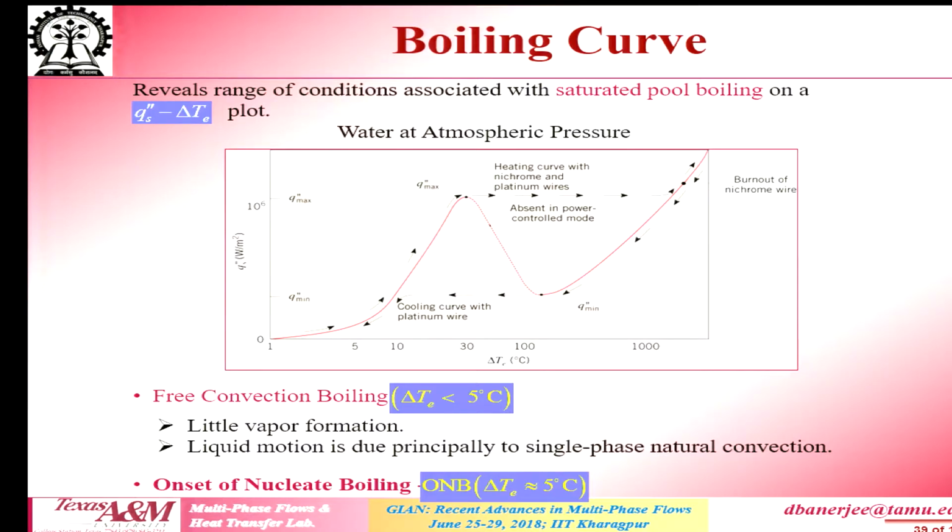In the film boiling curve, again it is pretty repeatable, I can go up and down this curve as many times as I want, as long as I do not hit the minimum heat flux point here, or the Leidenfrost point. It is a fairly repeatable experimental protocol. But in between, this whole thing becomes a little uncertain, what is known as transition boiling.